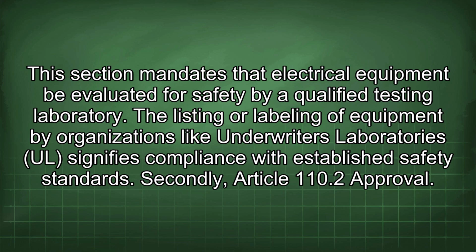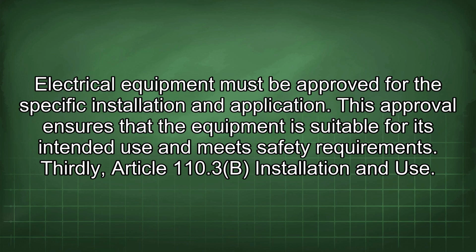Secondly, Article 110.2 Approval. Electrical equipment must be approved for the specific installation and application. This approval ensures that the equipment is suitable for its intended use and meets safety requirements.